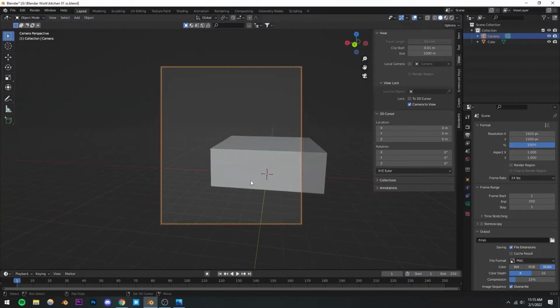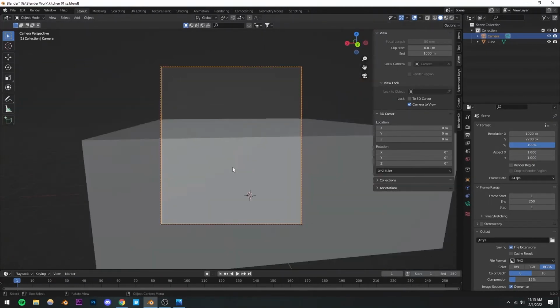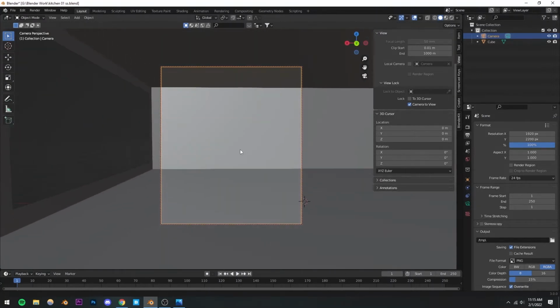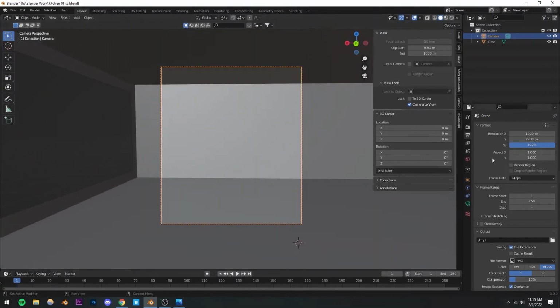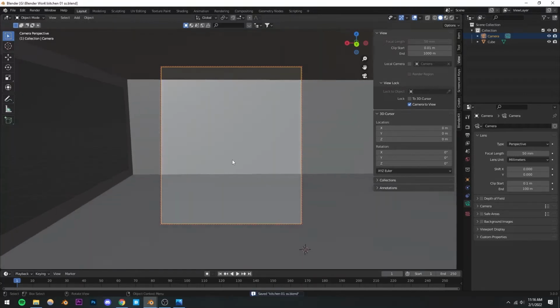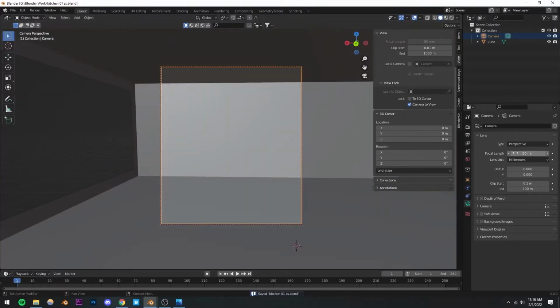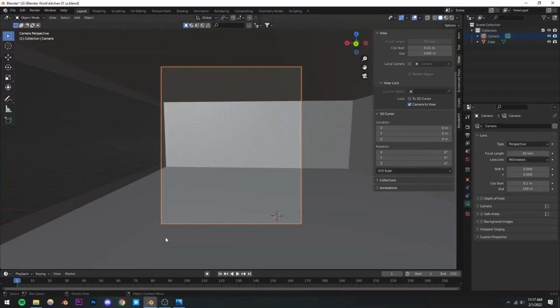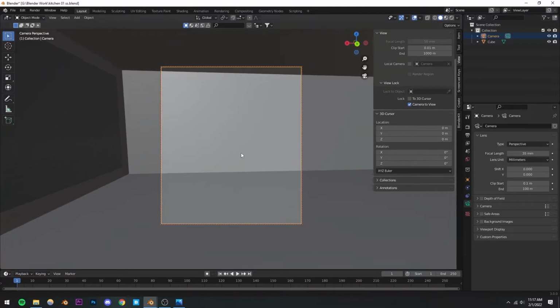Okay, perfect. So next up, what I'm going to do is go inside my camera, and we're going to set our perspective, or what do you call it, our camera focal length. Now that is very important. Yeah, so I feel like since this is an interior render and we are basically just shooting an indoor scene, I think something like 50 is way too high for us. On average, your iPhone camera has a focal length of around 26 millimeters. I'm just going to set it to something like 35 because we don't want it to be as wide, but something like 35 should be good.